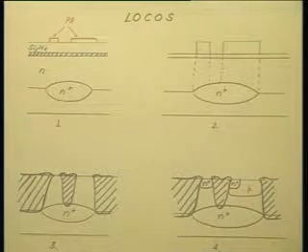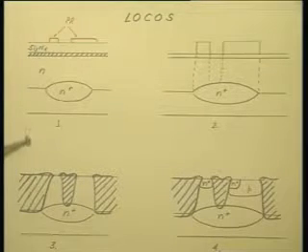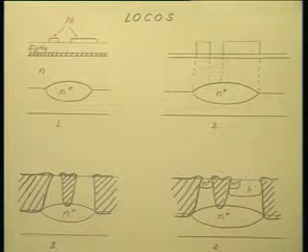So, this is a recessed oxide LOCOS isolation technique. Recessed oxide is used in order to improve the planarity of the device. Of course, without recessing also you can use the oxide isolation technique. In that case, the top surface of the oxide will rise above the actual device surface. So, there will be a loss of planarity.